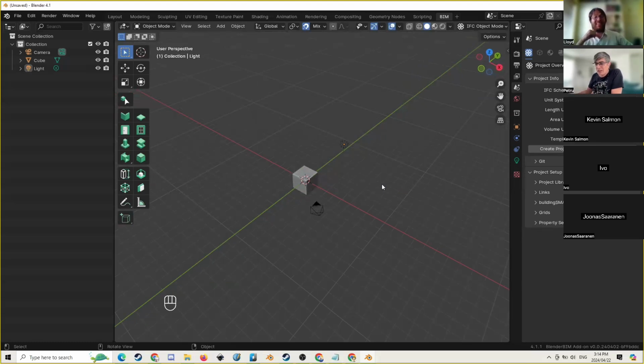We have a question here, and let's just clarify that because you mentioned now this. If you just save to IFC with a DXF, does it not get saved? Yeah, no, it won't get saved. So you would need to classify the DXF as an IFC class for it to be saved. And even then, each layer inside of your DXF would need to be individually classified. So it's a manual process at the moment.